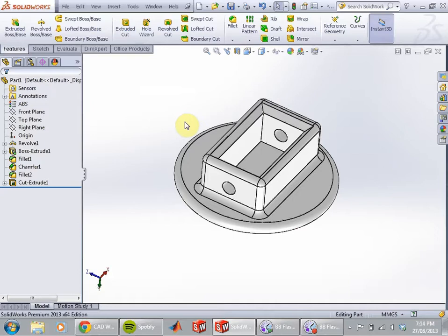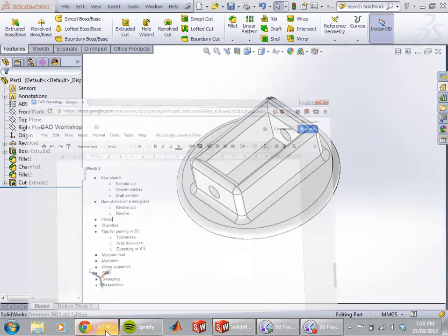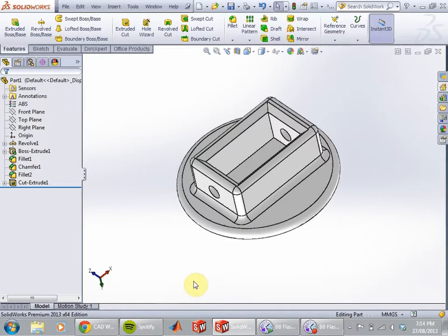With 3D printing, the part shrinks by 0.2 millimeters, even a pretty large part. So if you wanted to put a bolt through the material itself and you don't put enough clearance in, it's not going to go through. Stuff like that. You can do 1 millimeter thickness, but it's really thin. It's almost springy at 1 mil. You can bend it, it's easily bendable. 3 mil's good. 3 mil's really solid.